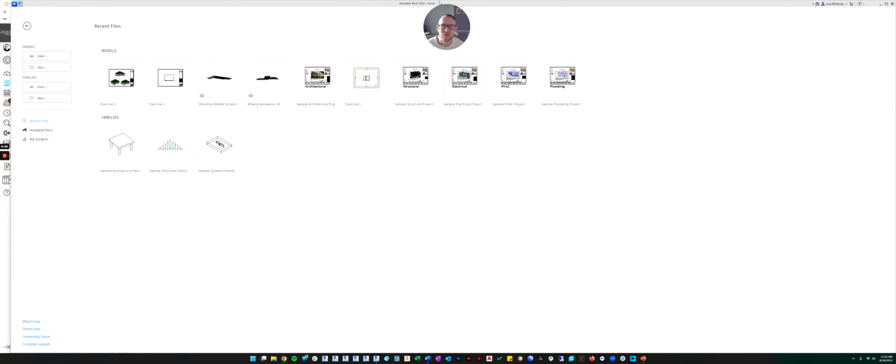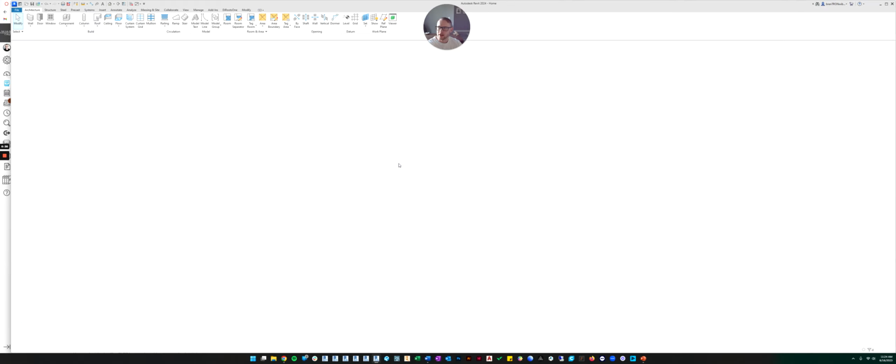All right, so for this video, we are going to be creating a new Revit project, and we are going to build a building from an existing plan. So with that said, you'll need to launch Revit, and instead of clicking on a previous project, we're going to start a new one. So we're going to go over here to Model, and we're going to do New Model, and we're going to use the Imperial Multidiscipline template. And we're going to create a new project and click OK.